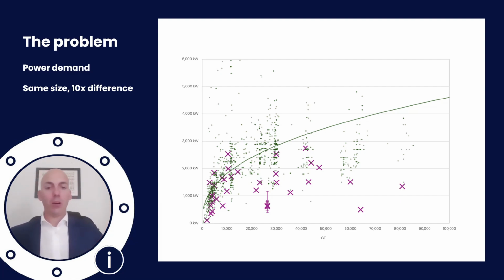As you can see, a lot of information is above, a lot of them is below, but this is the best fit for this information. Container ships do a better fit, by the way, but we'll show a few of them. And then the fuchsia, actually the pink dots or crosses, and the box plot that you see with the crosses, those are either true measured values over time, so real-time measured values, or validated values either by ship owners or onshore consumed power indications.